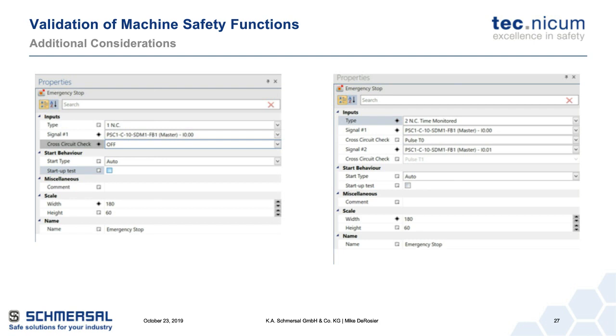In other cases, we found that because there were integration lines and the machines were being supplied by different manufacturers, but it was one integrator putting them together, jumper wires in terminal blocks were left in, even though the external e-stop circuit was wired in. They forgot to remove the jumper wires that came from the original OEM. So when they went to do a global e-stop on the machine, only that machine shut down. None of the other ones did as it was supposed to. Found the jumpers, removed them, but it was by doing those visual inspections.